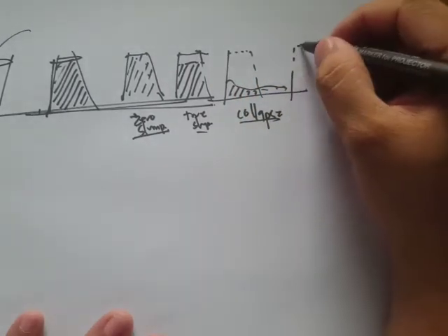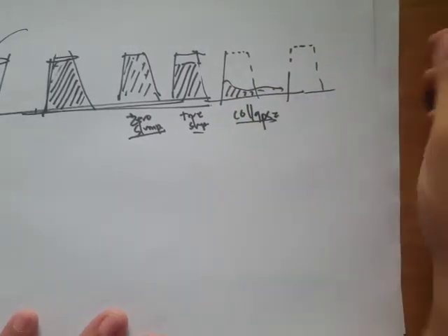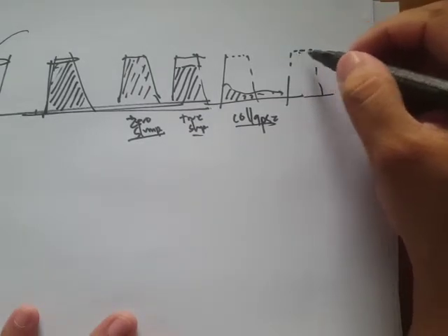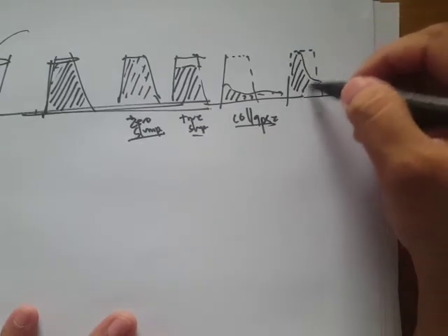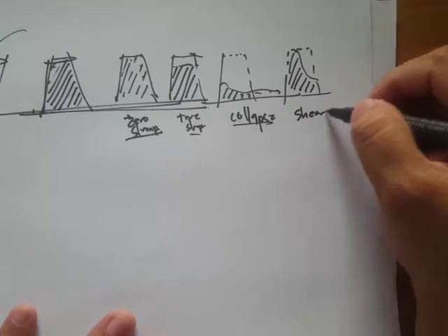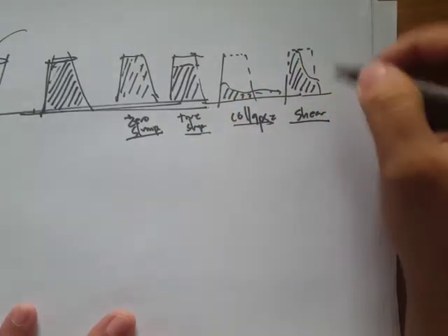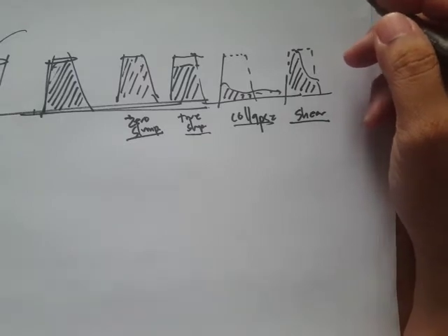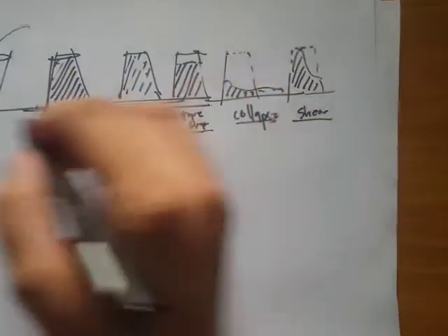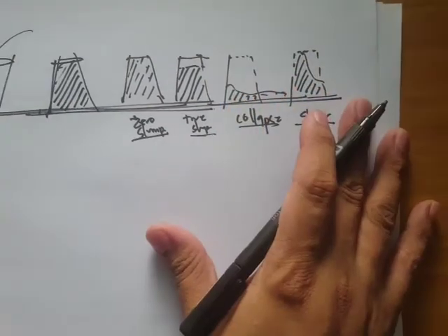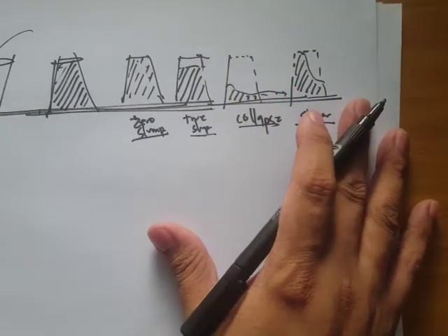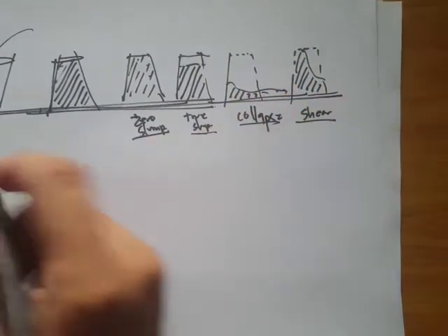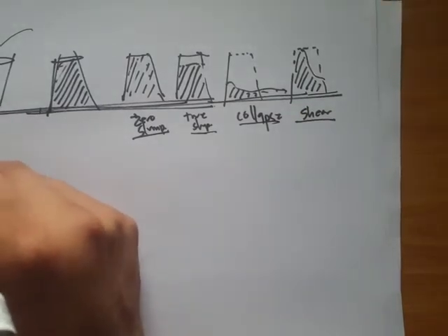And if you have, let's say, only a portion collapse, that's what we call a shear slump. Meaning probably it's not mixed properly, or not mixed well. Okay, so a detailed discussion about the slump test can be found in our lecture handouts. Next, we'll move on to the topic on mixing proportions.